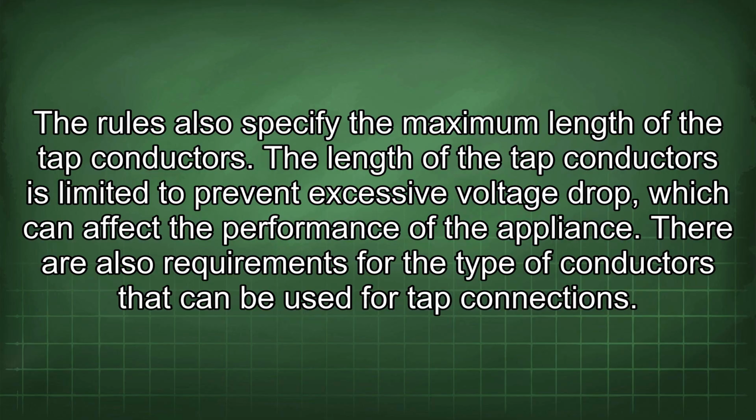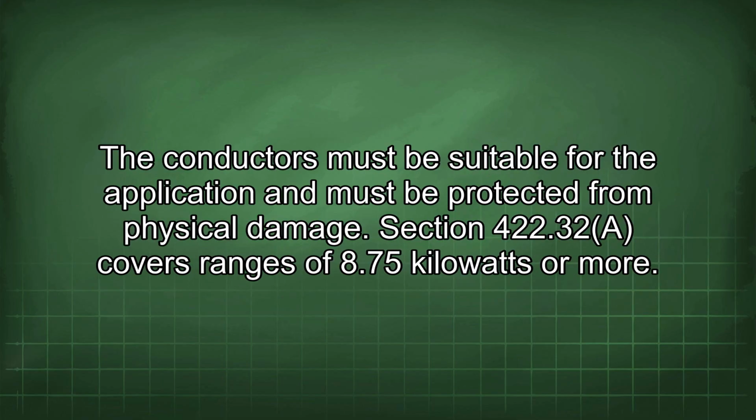The length of the tap conductors is limited to prevent excessive voltage drop, which can affect the performance of the appliance. There are also requirements for the type of conductors that can be used for tap connections. The conductors must be suitable for the application and must be protected from physical damage.